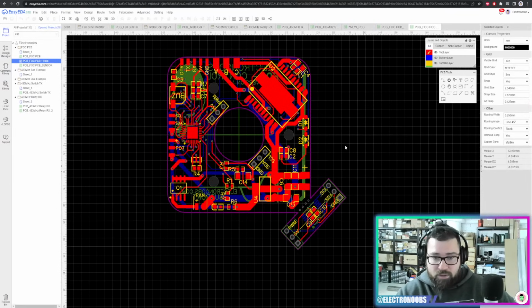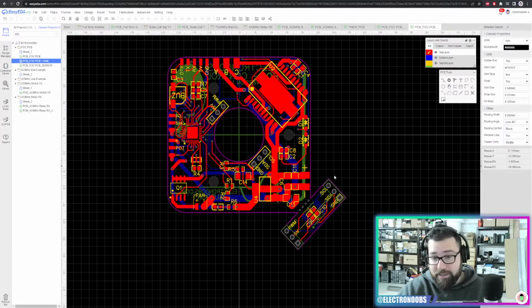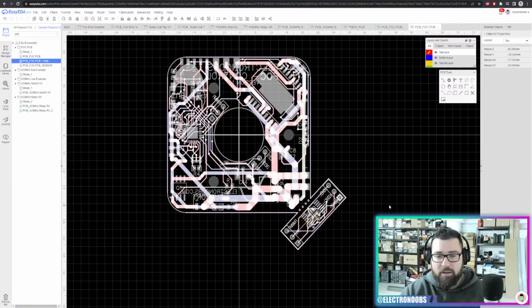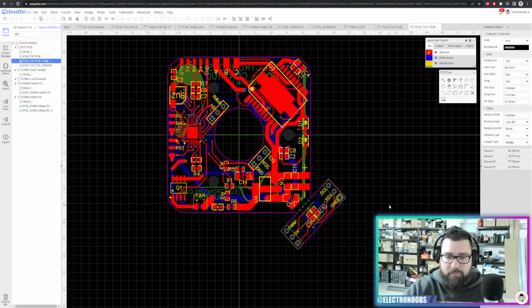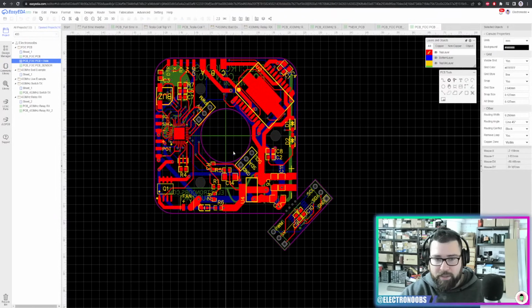So when you ask this to be manufactured, you will receive this PCB, and all you have to do is just snap this PCB and break it, because this part is supposed to go over here between these pins on top of the PCB. So instead of just making two PCBs and paying double the money to the PCB manufacturer, I've made two PCBs on the same design. So I send this to PCBWay just as if it were one PCB, and then just use these vias here to break the small PCB and place it here.